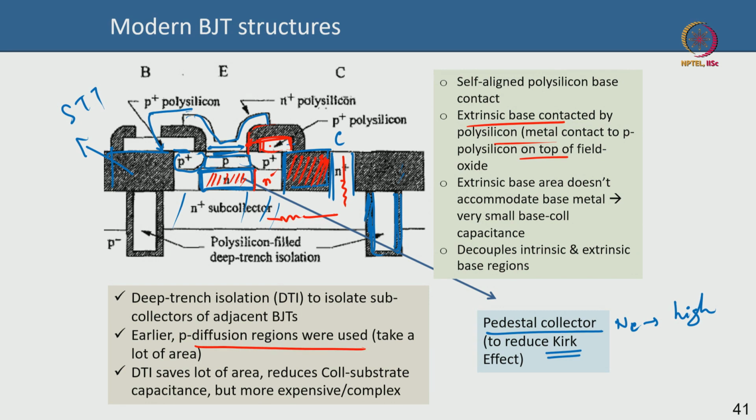And then you have to have good isolation between different components, that is of course obvious, but we will talk more about this when we talk about silicon germanium HBT, because there we can discuss many of the things in more detail. Why? Because silicon germanium HBT is more mainstream now, the BiCMOS process. It helps achieve better device, or I would say system performance. When you combine silicon germanium bipolar devices with RF CMOS, you tend to get more benefits for the same cost, okay, or you can reduce the cost for the same performance.